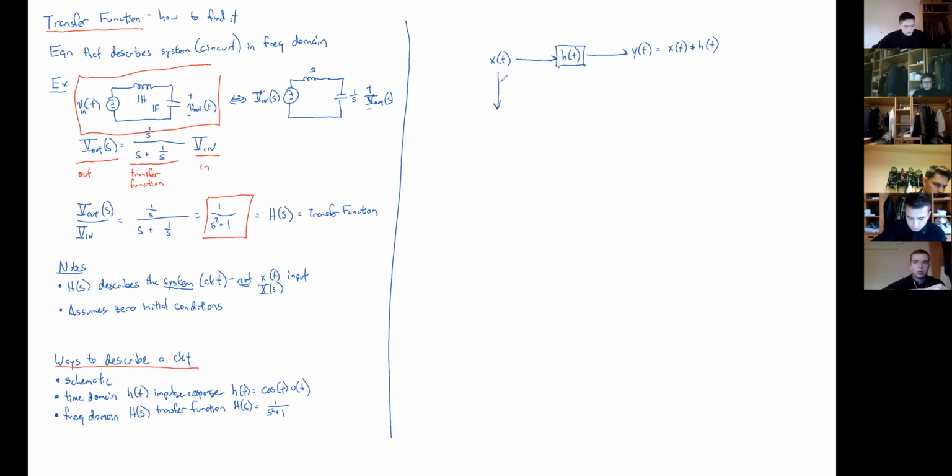But you also know how to take the Laplace transform of the input. That gives you X(s). And the crazy thing is this h(t), which was what you got by hitting it with a hammer, the response of your system to an impulse in, happens to have a Laplace transform of H(s), which is what you derive down here without any impulses being involved. h(t) has a Laplace transform of H(s).